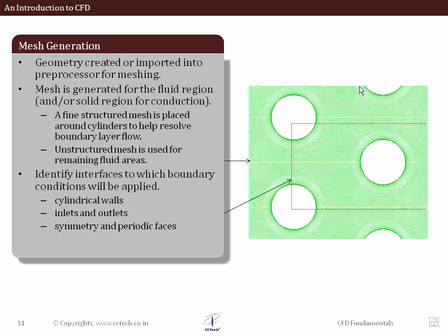But as you can see here, we have taken only a section of the geometry. Again, what you can notice here is that we have generated something called a mesh, which is discretization of the geometry. In this case, what you can see here is like we have a nice boundary layer. You'll get familiar with these terms as the course progresses. Just you can see that we are interested in capturing the flow phenomena, especially around these tubes, the cross section of the tubes that you can see here. And we have the overall system being modeled.